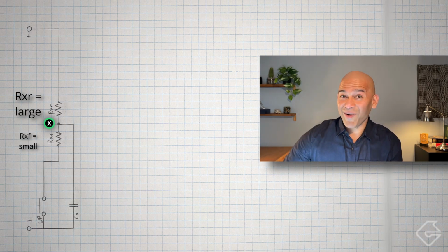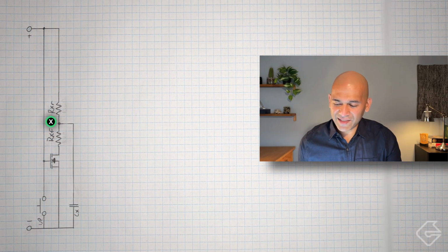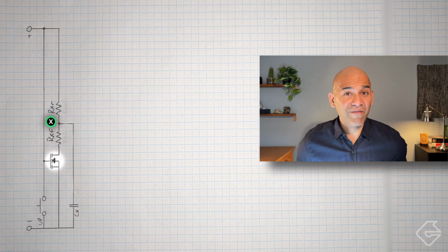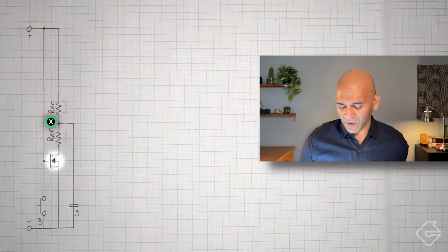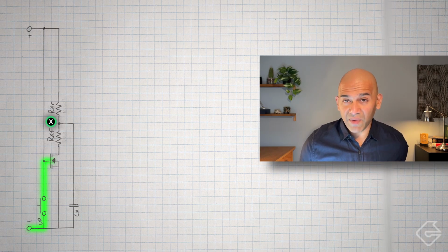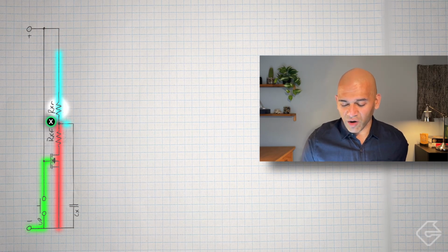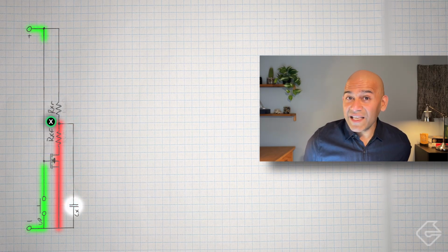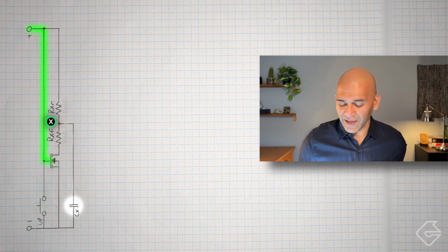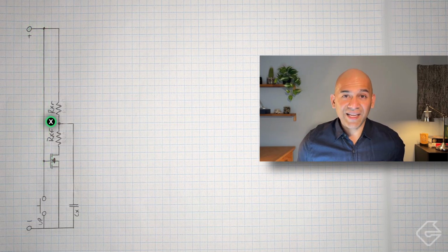Well, we can do that. We have MOSFETs for that purpose. Here's the same circuit, but with the MOSFET added in. And the MOSFET in here does one thing. It inverts the signal. So imagine when this button is pressed. When this is pressed, the point over here is actually going to be 0. It's going to be grounded, which means that this MOSFET is disengaged. If this MOSFET is disengaged, when I push this button, the charge path is lit. When I release the button, that engages the MOSFET and the discharge path is lit. So this MOSFET allows the button to take action when we press it and discharge when we release it.